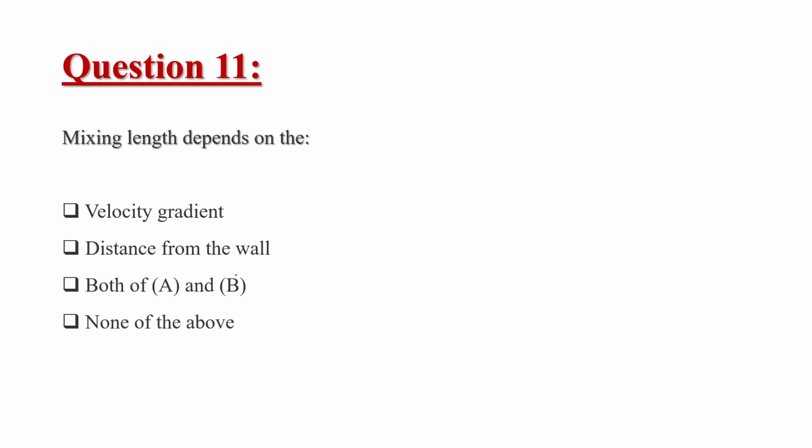Just substitute in here, what we will be getting is that u max is equal to, we have a h square which is equal to 6 times u mean, so we have 6 times u mean by 4. Which is nothing but if we cancel it, it will be 3 and it will be 2. So this implies that u mean is equal to 2 by 3 times u max.